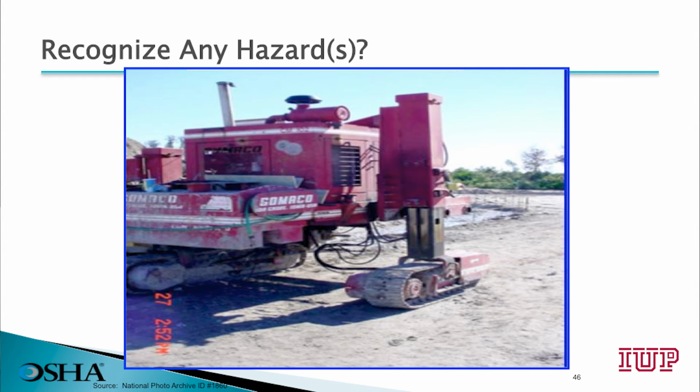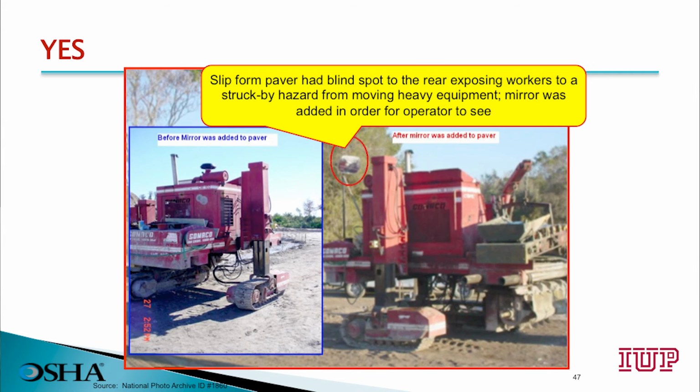Can you recognize any hazards? A slip-form paver had a blind spot to the rear, exposing workers to a struck by hazard while the equipment was moving. In this case, a mirror was added to help the operator see.